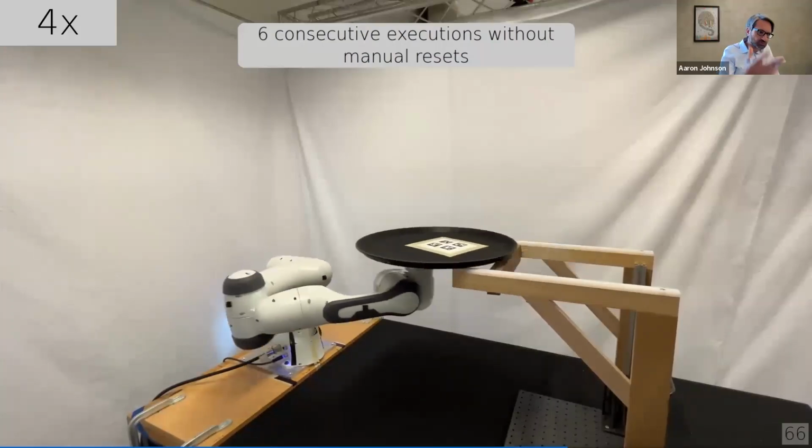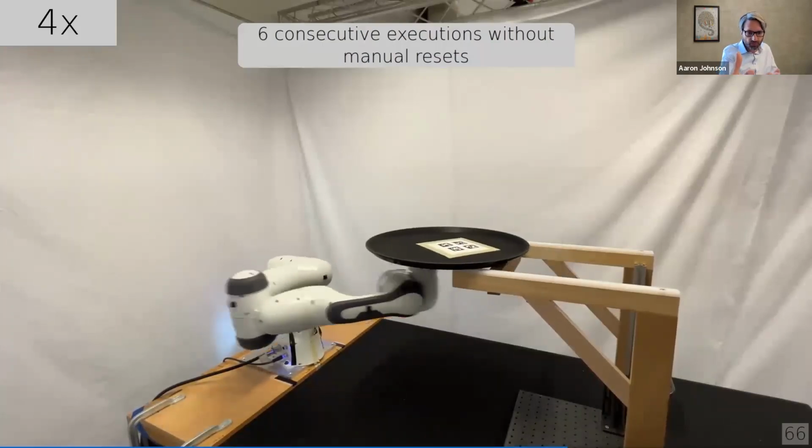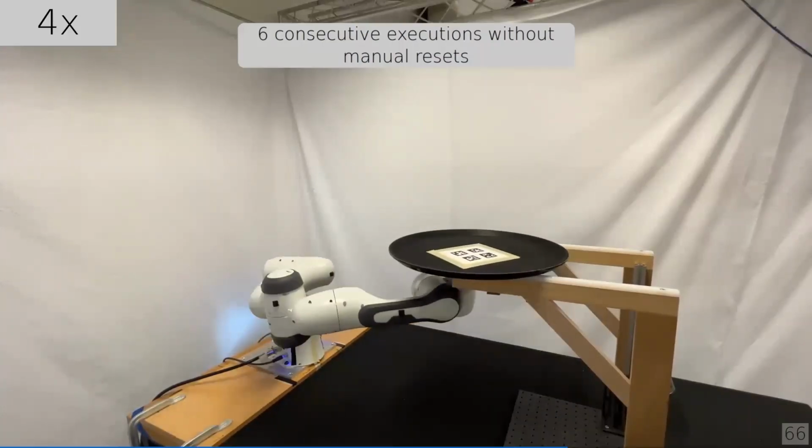If you're going to have to paw at it multiple times, if it had just lifted straight up and moved a little slower backwards, wouldn't it have worked the first time? Yeah, you can imagine that if you're very careful, you can try to do this quasi-statically, except you might have issues right when it transfers from being completely supported by the supports to just the end effector. You could do that. What we want to do is really leverage sliding, to force it to do it more dynamically. So this type of behavior of going faster but maybe missing a few times was something we actually optimized for when choosing the gains.